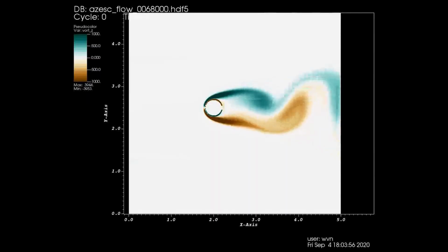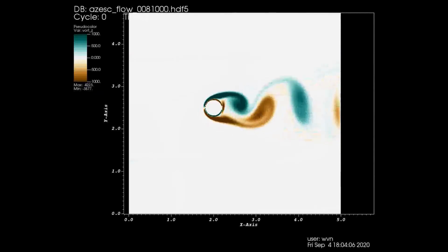Something that's useful in understanding these equations is something called nondimensionalization. Nondimensionalization is where we take a number of quantities that describe the nature of a flow, and we arrange them in such a way that all their units cancel out. So in the case of a simple subsonic flow, perhaps we have the density, we have some kind of length parameter, like a radius if you're looking at a cylinder or something, and the free stream velocity, or essentially how fast the bulk air is moving.